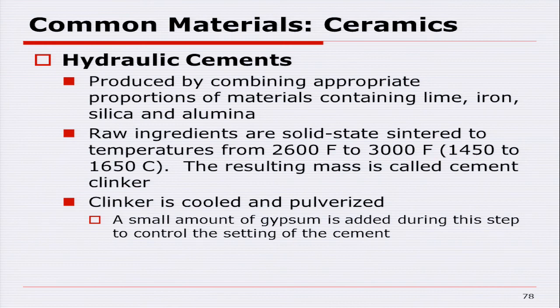And then we talked about cements, and we call these our hydraulic cements. Basically what we're going to do is take different minerals that give us a certain percentage of lime and iron and silica and alumina. And it depends on where you are in the United States or in the rest of the world what actual resources you're using to come up with this combination of minerals. And you heat them all together,